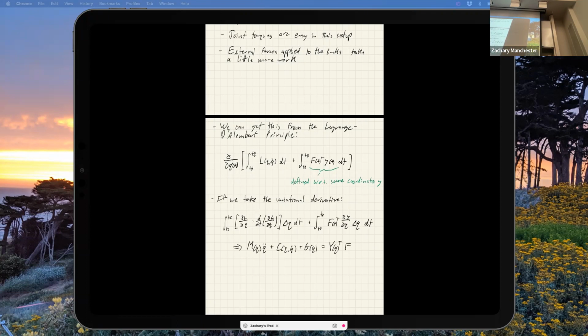So this is the Hessian of this guy, right? And it's sort of coming from this term, right? This guy is this Coriolis term, comes from some weird mass matrix derivatives that we just saw. It's that mixed partial term. Gravity terms, right? So it's just partial potential with respect to Q. And then this is the external forcing term. This is the Jacobian that maps us from whatever weirdo coordinates outside the robot we choose into joint space. And then this is the force in whatever weirdo outside world coordinates we liked.